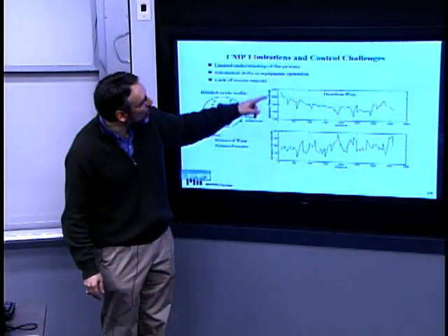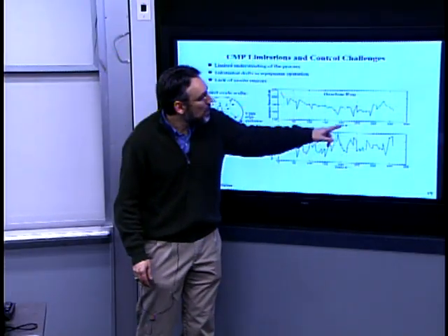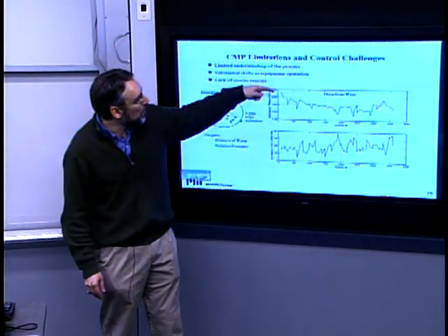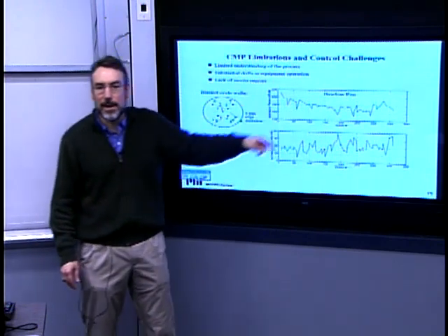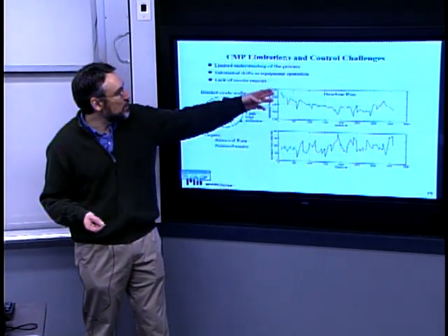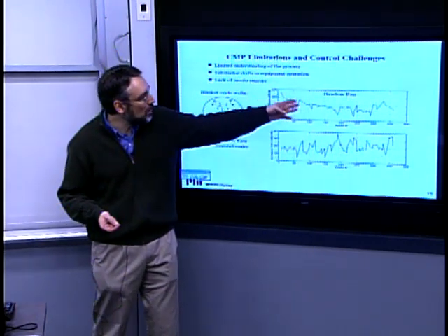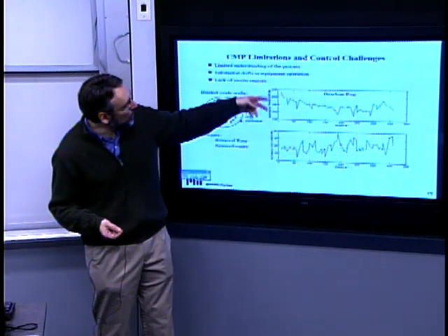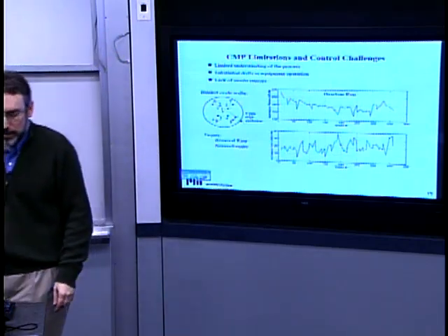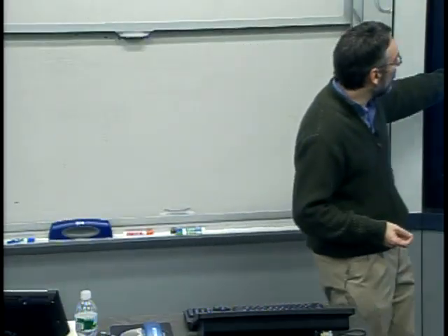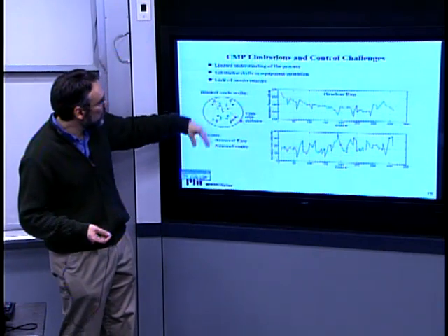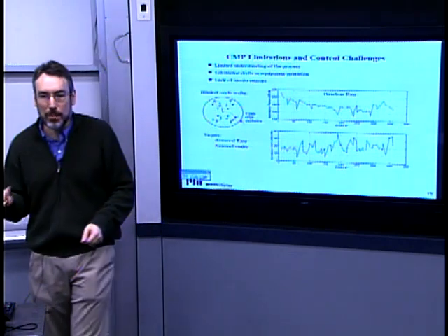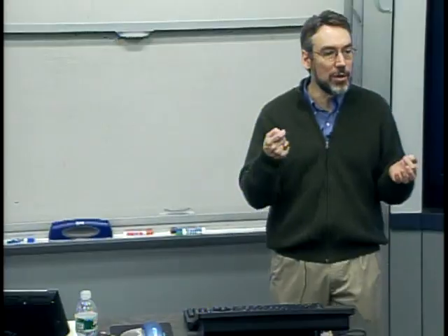And if you looked at the normalized removal rate for a 350 wafer sequence, you will often find drift in the removal rate. You might start out with a fairly high removal rate, and over time it drifts down. And this is something like a 20 or 40% kind of drift. Similarly, if you looked at the wafer, measured some pattern, some 8 sample point, and calculated a non-uniformity metric, maybe its standard deviation of those points,